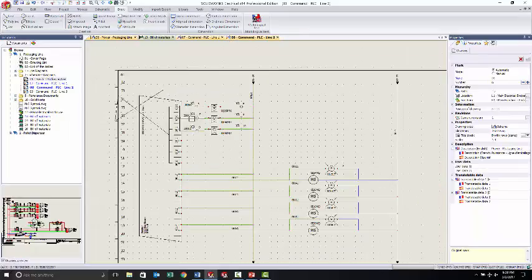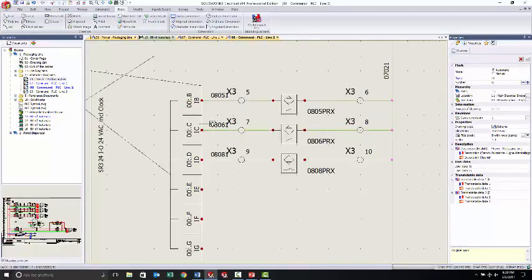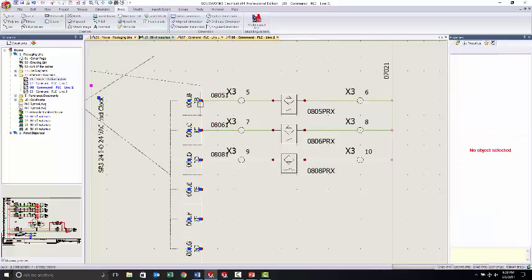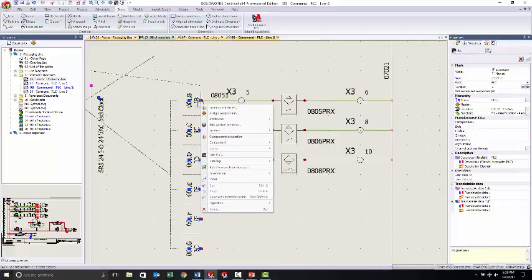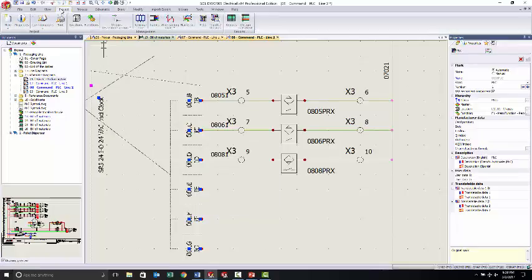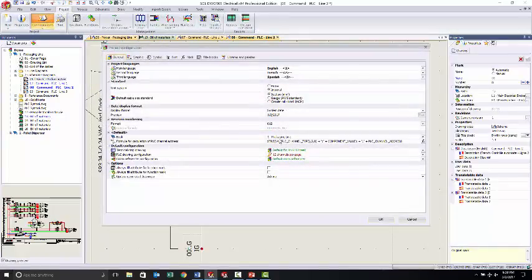large on my view. Now, if you look at this specific PLC, yes, we've already garbaged it up a little bit. I can make a change to this PLC to actually show. Under your project, you have the channel configuration of your PLC here. And notice it is specifically calling out the PLC channel address. In 2017 SP2, they have fixed this so that the top PLC actually works all the way down through all of the PLCs to give you this address.